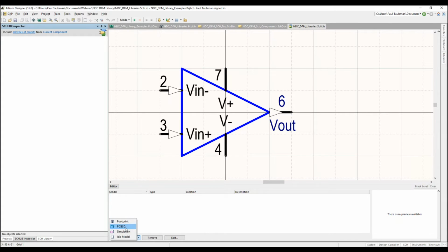I talked quite a bit about this in a prior webinar I did a couple of months ago, so take a look at that. But the short of it is this: do not use this, all right, unless you actually are using the legacy 3D stuff, and I don't recommend it. The new stuff is far, far better and easier to use. We don't attach the 3D body to the symbol anymore. We attach it to the footprint, and we've been doing that since 2008.